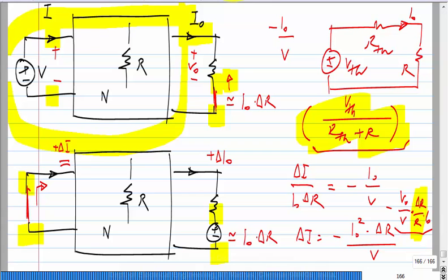Okay. I mean, there is nothing wrong with resolving the whole circuit, I can do it. But maybe you are asked, let us say there are 1000 resistors, and you are asked what happens if there is 1% change in this, what happens if there is 1% change in that, and so on. So, you do not want to sit and resolve 1000 new circuits, right. As far as circuits are concerned, each time a resistance value is changed, that is a new circuit. Okay. You do not want to set up the whole matrix equations and resolve everything.